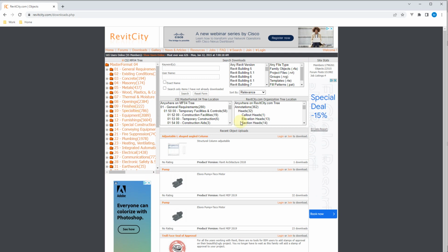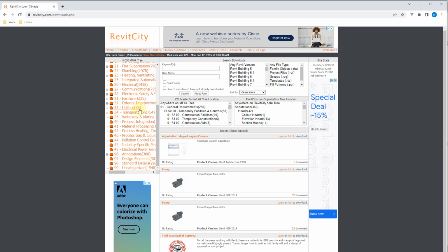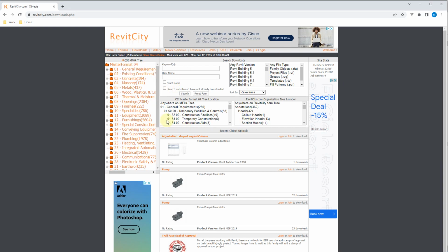Another problem is usually you load stuff from here into your new Revit, in our case 2023 Revit, and it was built in 2014 Revit, so it needs to update. The scale might be off, there's a bunch of problems with it. So usually you don't get as good of options from here, but there is more stuff here. Take that with a huge warning that you can get stuff here, but it's not going to be that great.